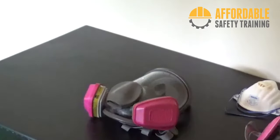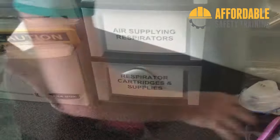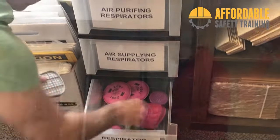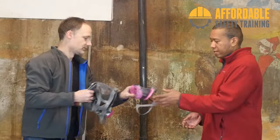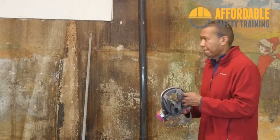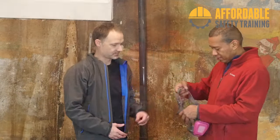Select a respirator type with the appropriate assigned protection factor for the work area. Select a filter and cartridge type that is appropriate for the hazard. A supervisor will provide guidance on selecting the correct respirator. Remember that you must be fit tested on the exact size and type of respirator that you are using.